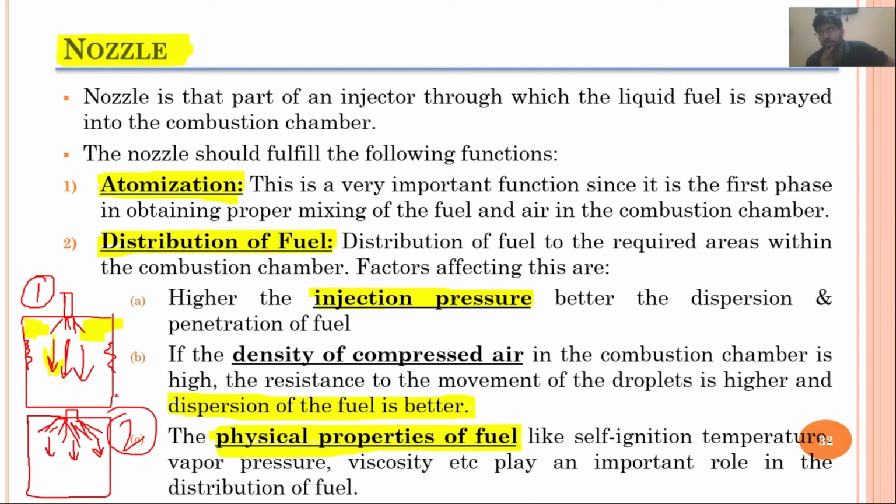has been sprayed across the walls of this combustion chamber, what will happen here is, since the temperature of the engines is usually very high, when this fuel gets in contact with the walls of this combustion chamber, instead of getting combusted, it will break down, and the carbon deposits will start sticking across the walls.